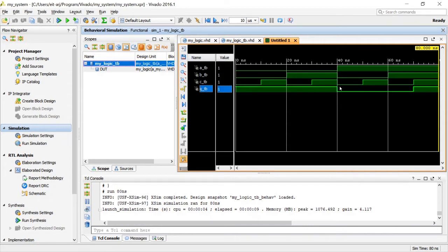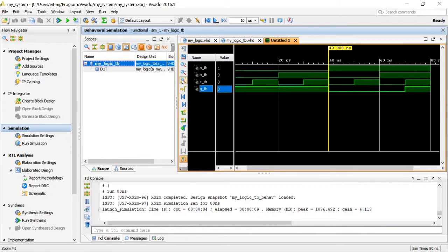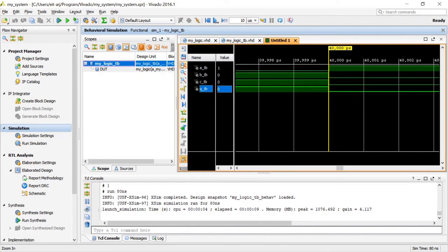We can also check another thing. So let's go to this falling edge of the output. And let's zoom in. So here we can see the simulation step, quite small step size. But the thing that I would like to show you is that as soon as the inputs change, the output changes immediately. So there's no delay or information about delays here. This is just a simulation that is performed on our description that we have given to Vivado. Okay, this looks quite okay to me.